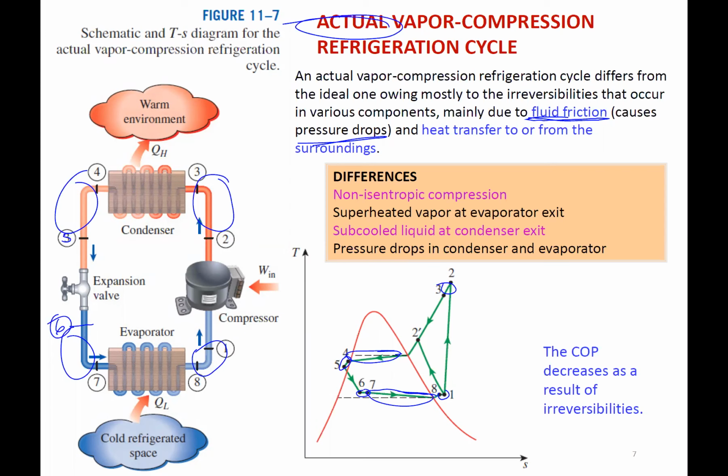Another thing that we have is what happens before the compressor: state 1 is superheated. So state 1 is not at a quality of 1. It's in the superheated region, and we do that to make sure, as the system's turning on and off, and with variability in operation, that it's never going to be a saturated mixture in the dome and see some liquid. Okay, so we superheat it just to be sure that the compressor is not going to see that type of fluid.